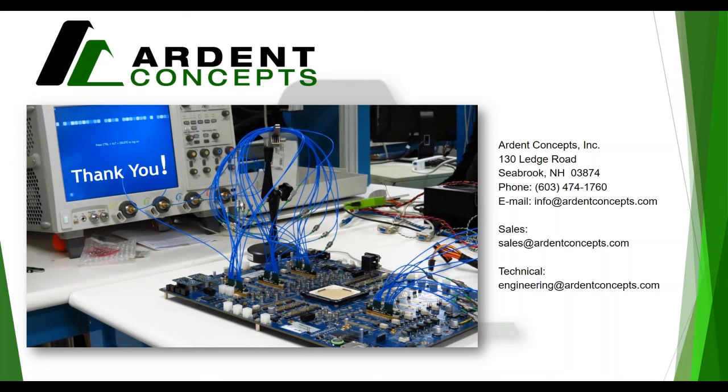With that said, Gordon, looks like one of the first questions we have here is, how do I de-embed this connector? So we will send you a S2P, S4P touchstone file depending on what you need. If you're using differential and you need to understand crosstalk between two channels, we can do that too. We have S4P files at the ready, or S2P files at the ready for all the cable lengths. So these are measured with the same fixture that you saw the results, so there's no printed circuit board. So we'll give you the de-embed fixture that you can add to your loss budget and see how you come in when you do your simulations.